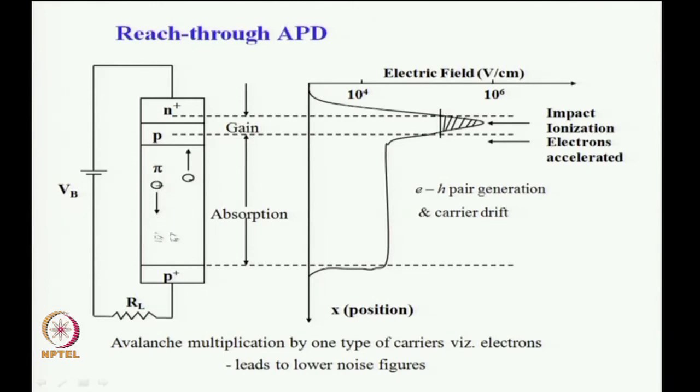This is why I call it the catchment area. The electrons get accelerated in this direction and holes in the other direction because of the electric field. However, the electric field in this region is not strong enough to accelerate the electrons to energies where they can generate additional electron hole pairs, so there is no avalanche process taking place in this region.